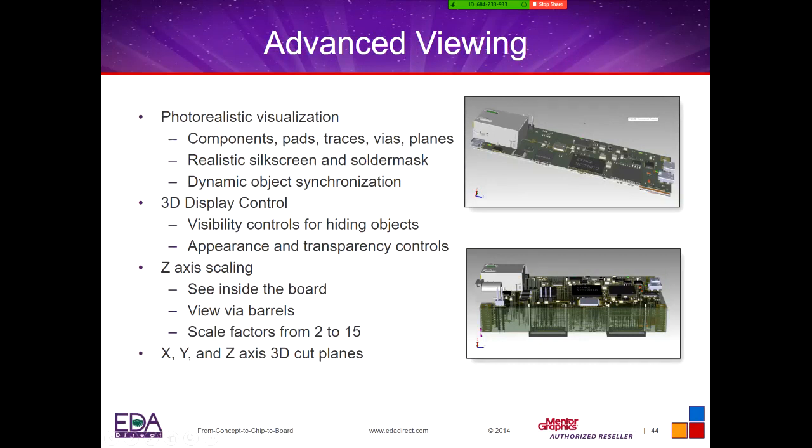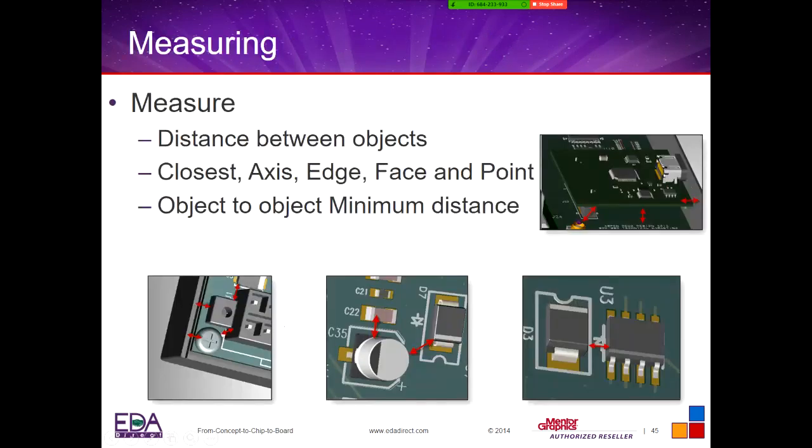to find out if we've made those connections. So you can cut the planes, increase the thickness size to be able to see how your connections are being done, whether you're doing blind and buried vias. Maybe you want to check to find out if anything's missing internally, planes, copper. So that's really nice. And then you're going to have a measuring tool inside of there.